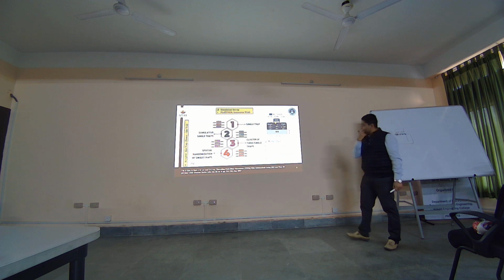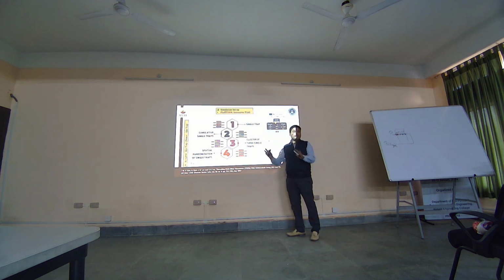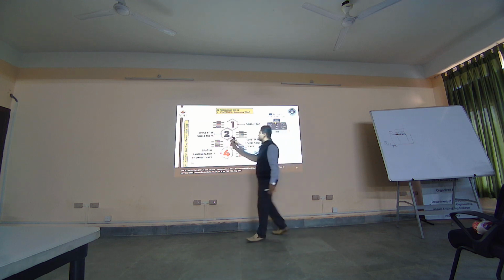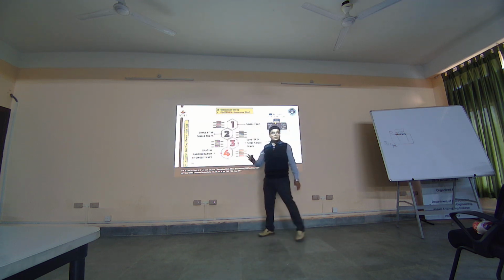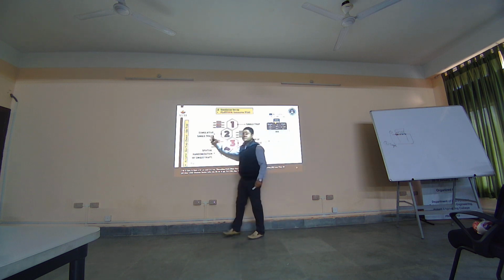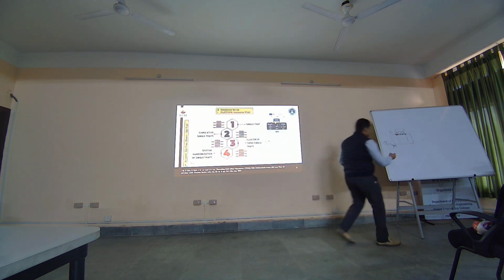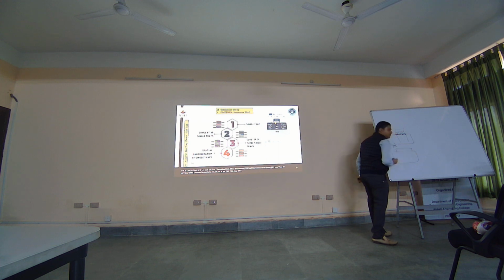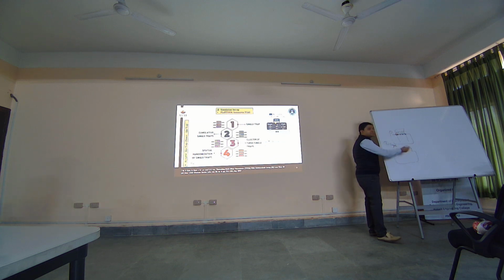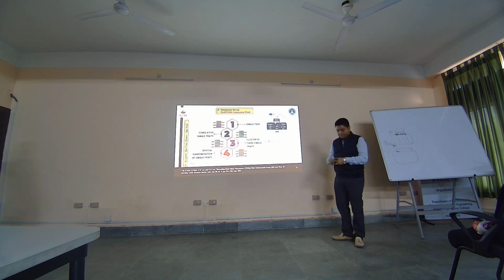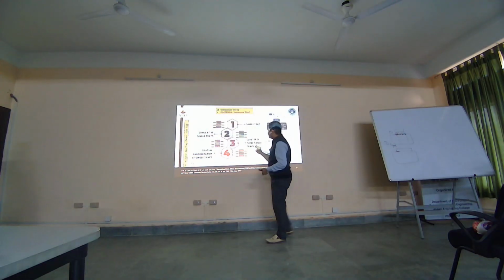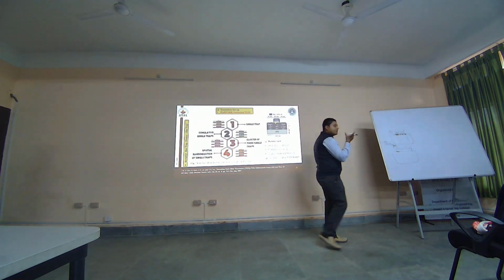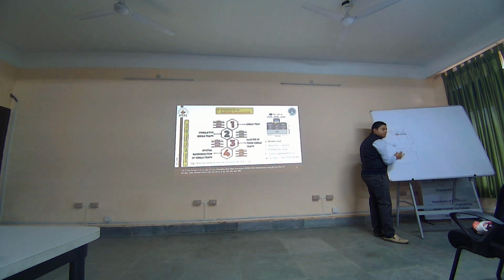These are the analyses. For the single trap, by definition, we placed the trap at different locations in the device and checked. Next was cumulative single traps. Cumulative single traps means suppose I have this interface. First I put one single trap and check the results. Then I check for two single traps, three, and I keep on increasing, and then I see which part is going to affect. And this is a cluster of three single traps. I will go with clusters: three here, next three here, then next three here.